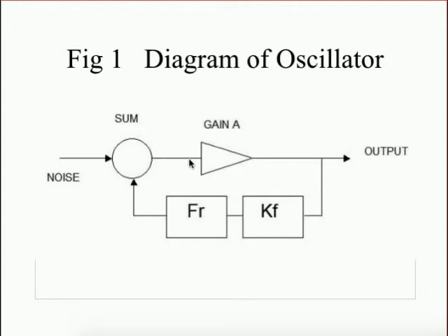The reason for this is that the amplifier isn't matched for a perfect power transfer. We want to optimize the signal to noise ratio, and the noise depends on the impedance looking back out of the amplifier into the load, and so the match that gives the best signal to noise ratio isn't necessarily the match for best power transfer.